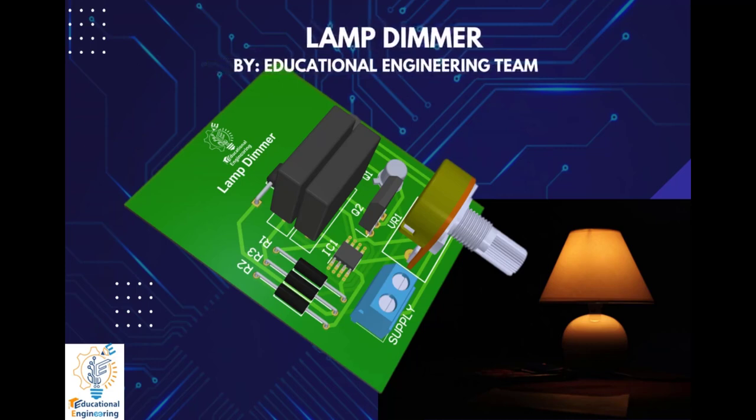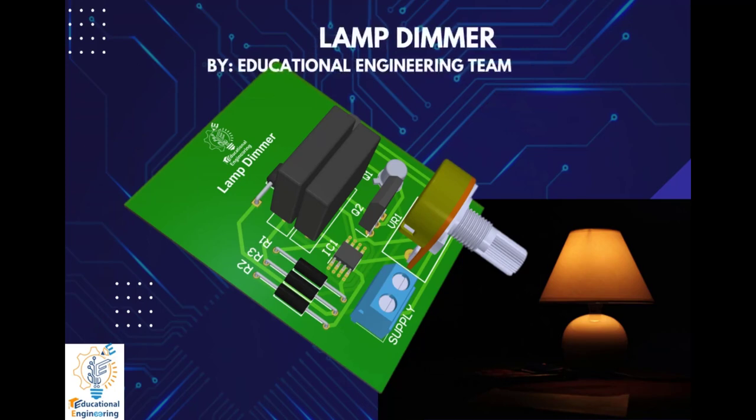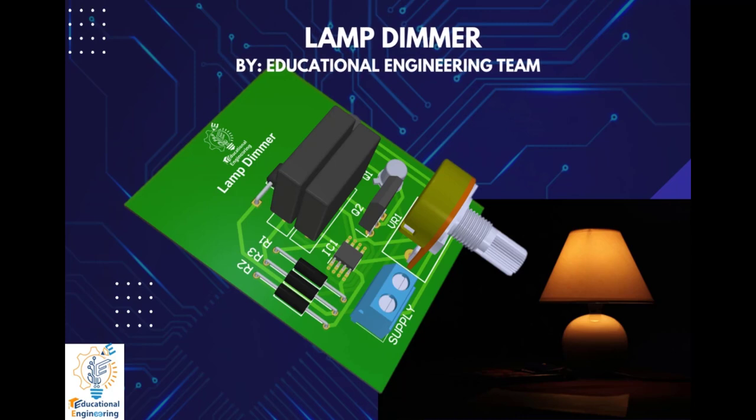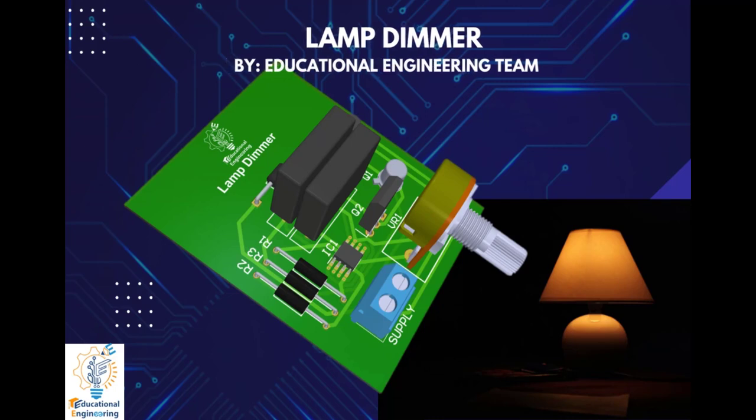In this circuit, the IC555 is wired as an astable multivibrator and it gives continuous square waves as output. The resistor and capacitors are the timing components. The duty cycle of the wave makes the lamp dim or glow brighter. The higher the duty cycle, the brighter the lamp glows, and the low duty cycle will make the lamp glow dimmer.